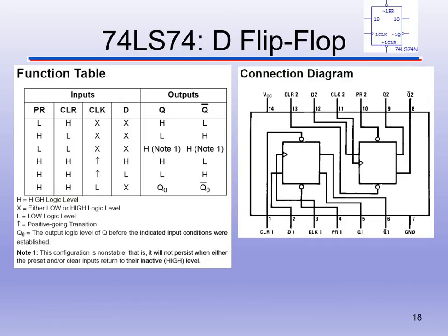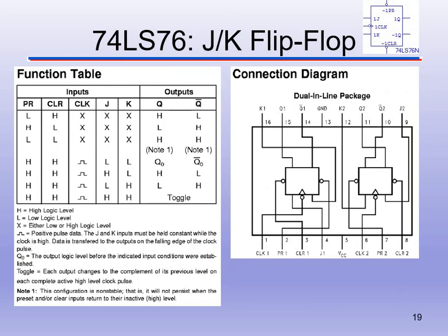And then when you pull it up, we can look at the data table on the data sheet, and we can look at the connection diagram. Remember, the connection diagram is going to be very, very important for us when we breadboard these. So notice it's the same as all the other chips that we've done. VCC is pin 14, ground is pin 7, so you need to make sure that you make all the connections correctly when we're breadboarding this.